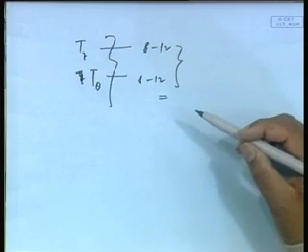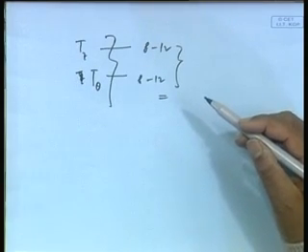So if it happens, you will have to try to see how I can separate them out. Even if you separate by 1 or 2 seconds is good enough, but you must separate out. That is an important thing. It has happened to practical ships that exist where heave and pitch periods are close by, and therefore everybody says they do not want to be on that boat because it is so bad motion.